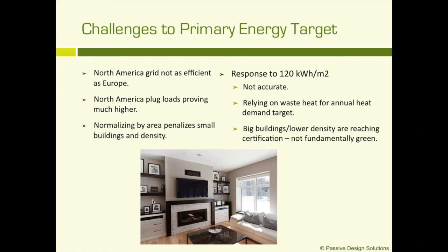One was about an 8,000 square foot office building, and one was about a 1,200 square foot house. And the 1,200 square foot house had a final ACH of 0.66, and it was one of our early projects, and we thought by putting in drywall we'd squeeze out that last little bit with an air tightness strategy and drywall, but we did not reach that target. The builder was celebrating really strongly with his 0.37 air changes per hour in the commercial building.